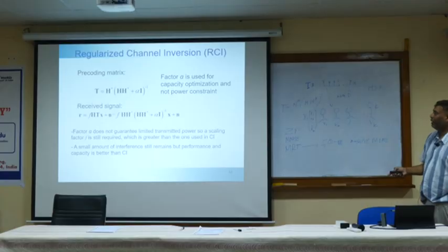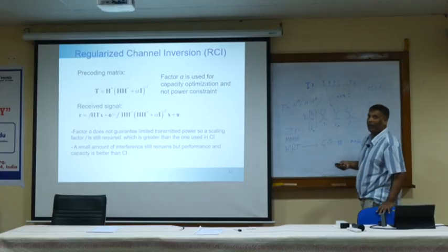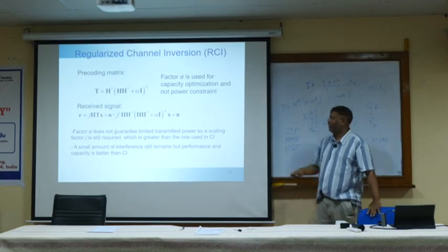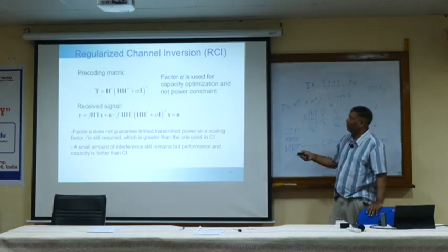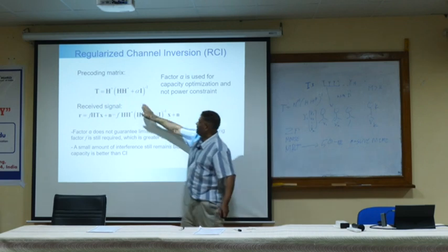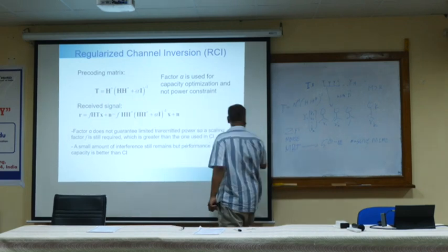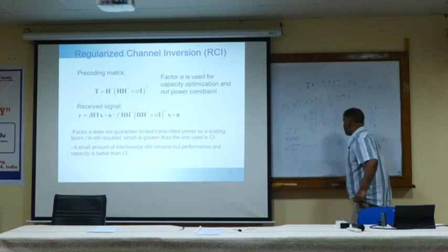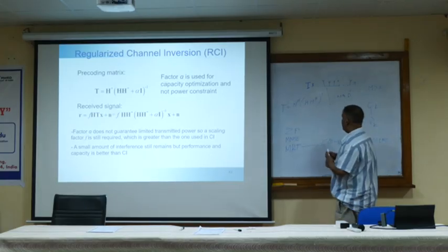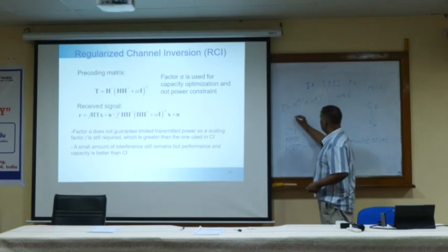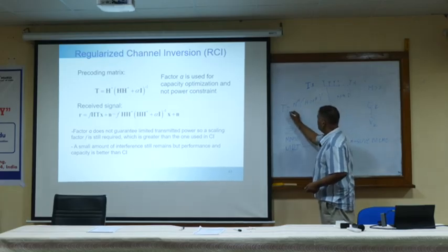Okay, so there's another precoder, similar to the regular MMSE precoder. It's called regularized channel inversion. There's an additional term here, alpha times I. So this is the MMSE precoder, and this is the zero forcing precoder.